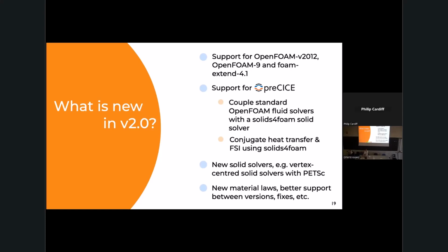Some other things, you can find the release notes online. There's support for preCICE, the training that was meant to be in this slot. preCICE, if you don't know what it is, is independent of OpenFOAM, but it's an open source coupling library. So you can couple different solvers. You could couple FEBio, which is finite element software, with OpenFOAM, or OpenFOAM with OpenFOAM, or pretty much any well-known open source finite element or finite volume library. You can couple them for FSI or conjugate heat transfer.